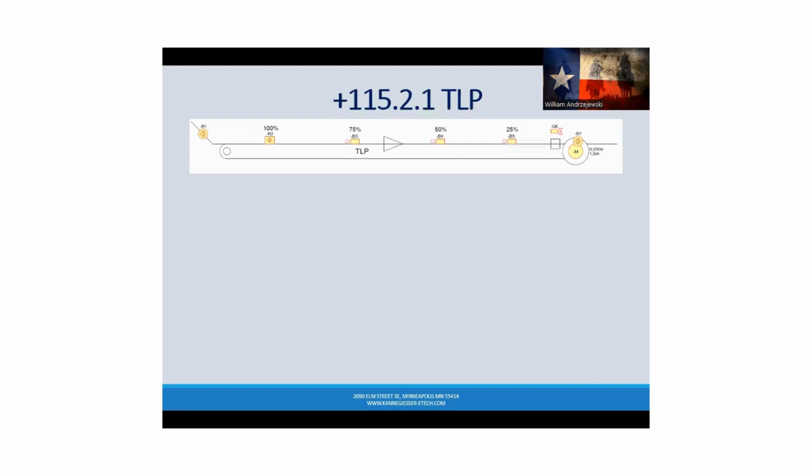All right, so we're going to go through this one in a little bit of detail just to give you some visualization. So we're going to look at B1. In this pictorial symbology it represents a rocker switch. So this is showing us B1 is this type of sensor. Item comes through, raises the rocker up, and the green proximity sensor over here is made.